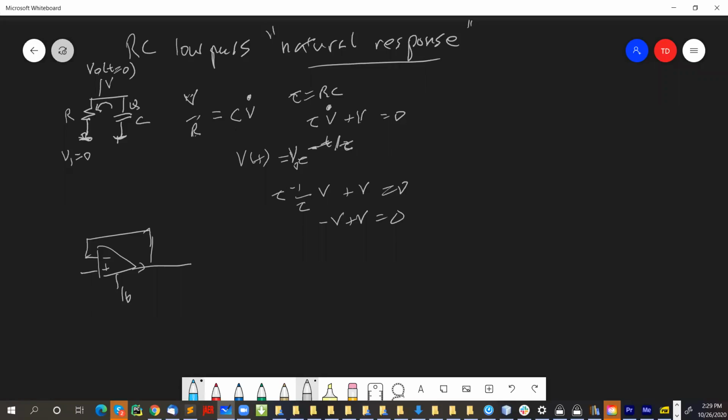So the I out here equals IB, that's the bias current, times, anybody remember what the function is? The hyperbolic tangent of kappa V over 2 UT. Let's assume we're subthreshold here. So that's the actual output current.